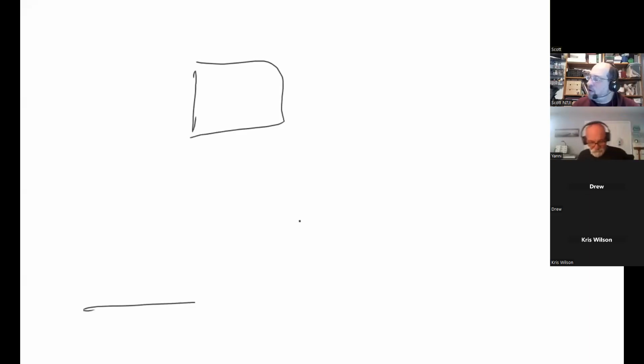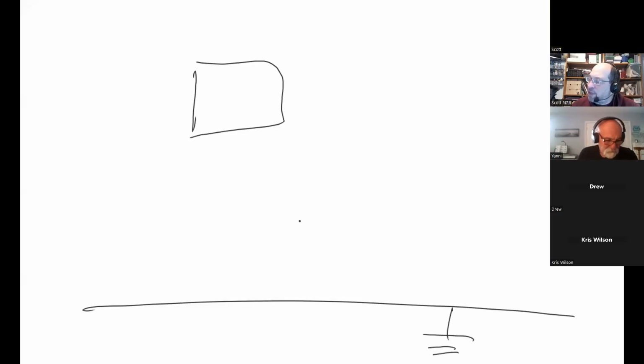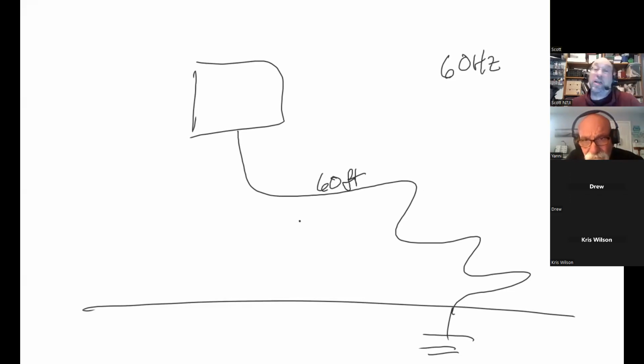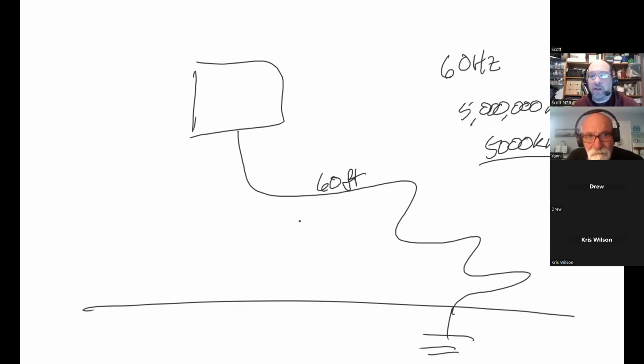The easiest way to describe it is, let's say you have ground down here, and here's your house or your equipment, and there's a cable that is, let's say, 60 feet to get to ground. At 60 hertz, what is the wavelength? Because 60 hertz has a wavelength. It's 5 million meters, or 5,000 kilometers. How long is 5,000 kilometers? That's like from the West Coast to the East Coast.